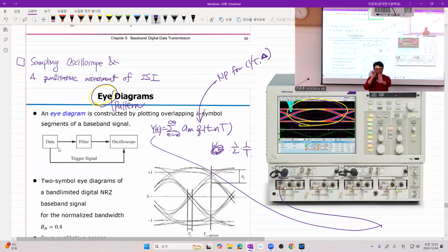When the electron hits the material on your screen, it absorbs the energy and releases the energy in the form of light. And it takes time. So if your symbol rate is very fast, before one line is brightened and darkened, the next line is also drawn, something like that. So you have a kind of delay, you have an overlap of signals.